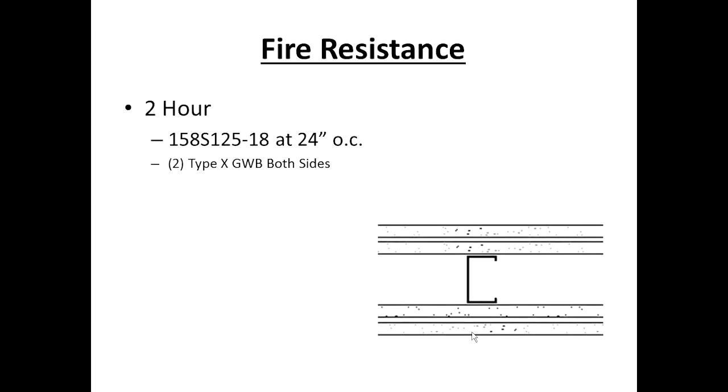Enough of the gypsum board stuff. 2 hours. Notice we've gone back to a 1 5/8 drywall stud, 18 mil, 24 inches on center, 4 layers of board. We basically doubled the amount of gypsum panel on that wall.